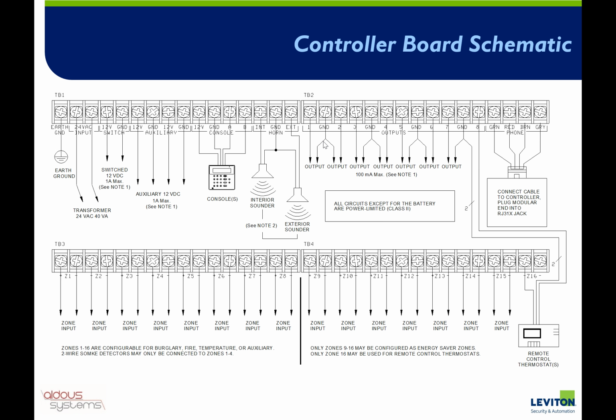So you've got 8 of those, and as you know, there's the expansion panel where you can add more with the expansion enclosure, 16 at a time. Over here, you've got the telephone dialer. This is where the telephone connection wires in. We'll cover that more later. And then down here, you've got 16 inputs. These are zone inputs for your PIRs and door contactors, or anything that gives you a volt-free contact closure that you want to trigger from.